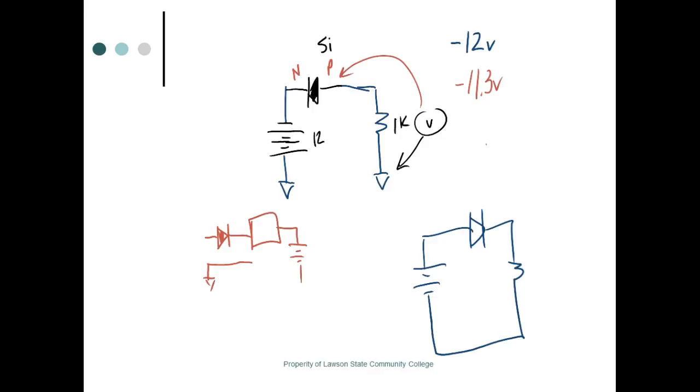But in this circuit, if they put it in backwards, it's not going to hurt anything because that diode is protecting the battery, right? You'll understand that in your charging circuit. So if I came up here for some reason and put a negative right there when it's supposed to be a positive, it's not going to hurt your phone at all, right? So most chargers, most computers, this guy right here has a diode in there. So if my cord breaks or this one goes out and I find another one that fits and I cram it in there and it has opposite polarity to my other charger, it's not going to hurt anything. Why? Because they've got that diode in there.